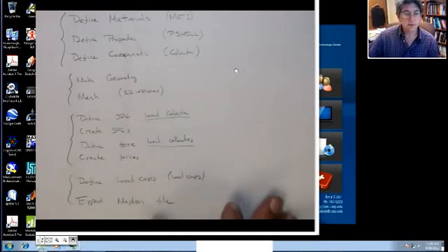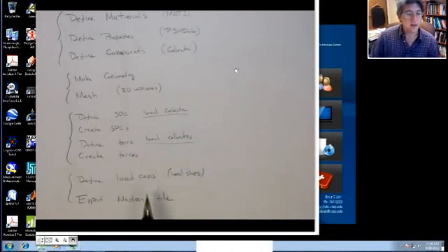The last thing we have to do is define the load cases and then export the Nastran file, until we can solve it in Nastran. All right? So we'll define the load cases and then we'll export the Nastran file. Actually, before we solve it in Nastran, I will open up the Nastran file and then edit it a little bit to put a couple things in that weren't put in with our Hypermesh model. In fact, you can define fully the Nastran model inside of Hypermesh, but I'm just going to do that just to show you how it works, okay? All right.